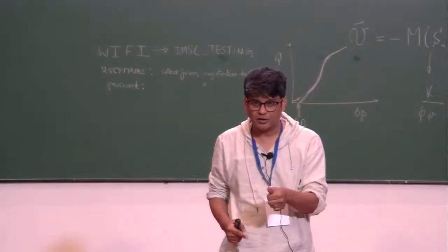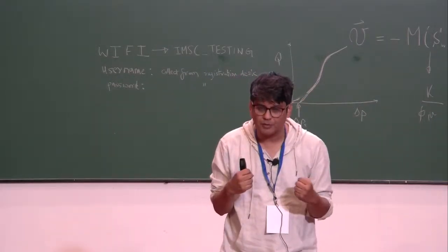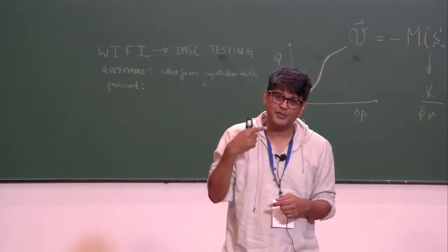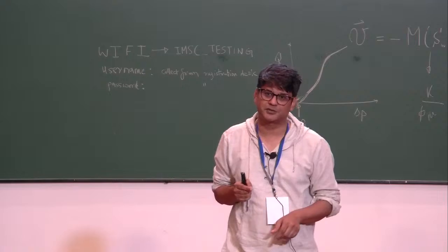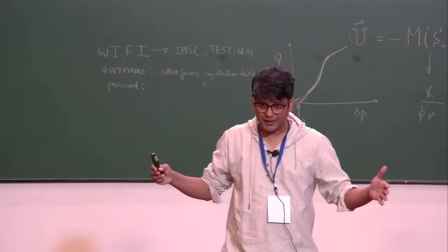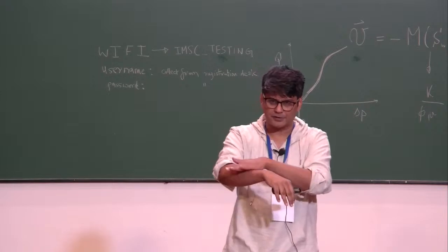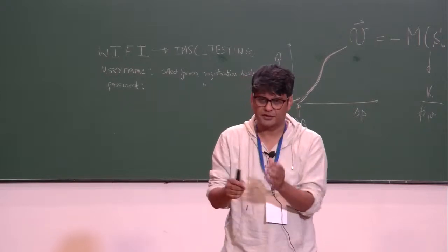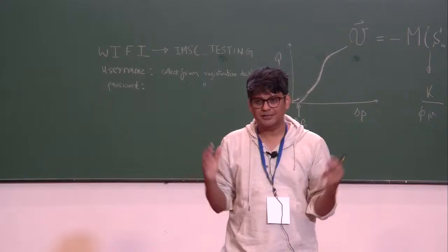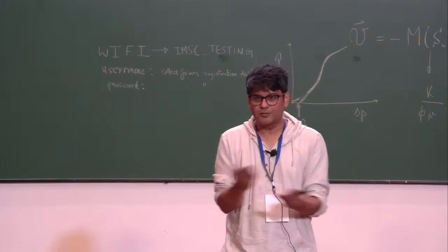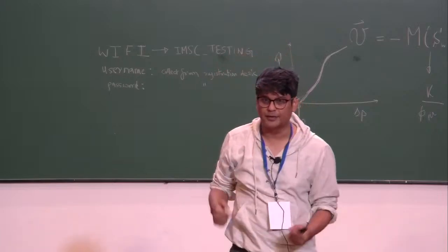Now the frictional component: what is preventing them from going back? Why am I being held at a much more compressed state? It is because friction is now much higher, because the orientation of the particle, the way it's touching the plate, has altered. In the first low density system, all these particles were flat on my system, so friction didn't change. But now these particles have got a little bit of splay, and that allows the system to support. Finally, it has to be a force balance. The force is coming both from the top plate and from the bottom plate.